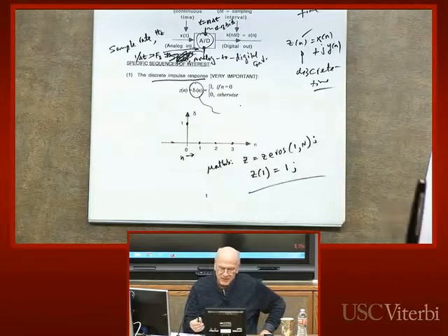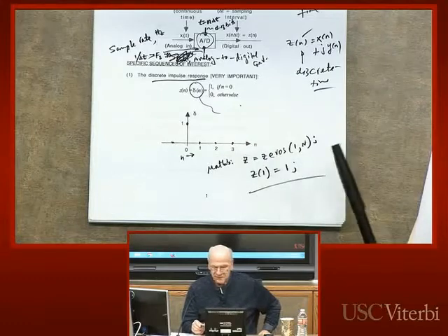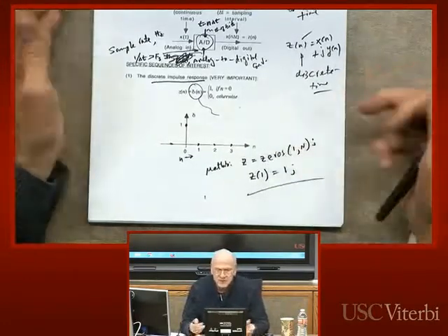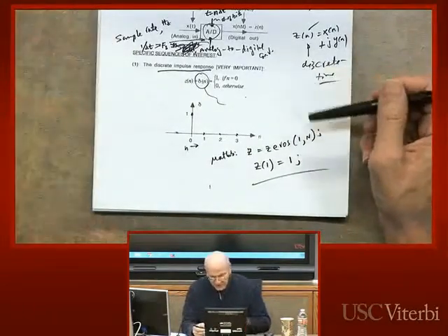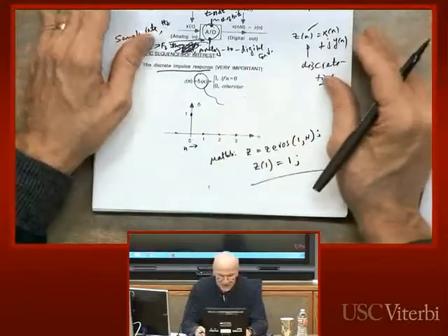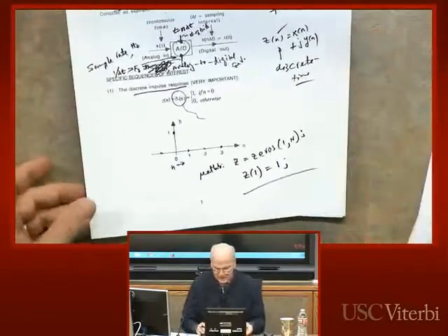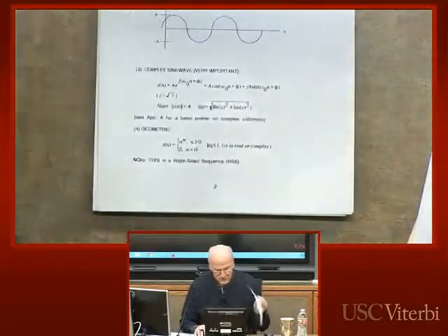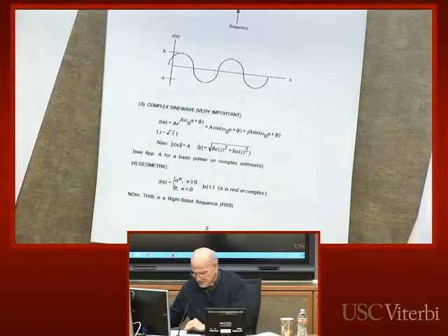But by definition, in Matlab, the length of the impulse response has to be finite. So if you're trying to use this impulse response to probe a digital filter, you typically will have to make n large enough so that you can see the full extent of the impulse response of the digital filter. We'll talk about that later as I discuss some examples of digital filters in the class. Okay, so anyway, that is the impulse response.